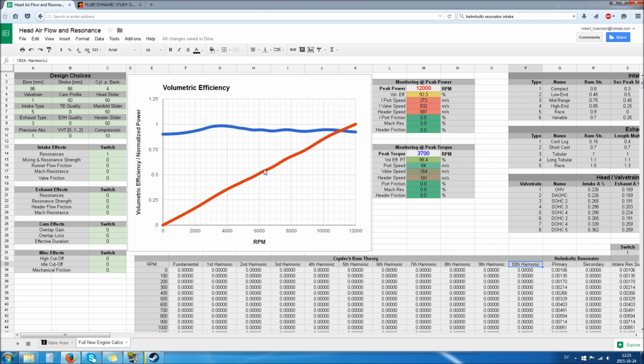And this bouncing back and forth can continue a while, as the intake valve stays closed. It is actually the second and third and fourth and fifth harmonic of this series which gives you some effects. That effect comes from when this shockwave gets back to the inlet valve, and that inlet valve is open. Then the shockwave will actually see to it that you get more air in than you would by only sucking on the intake runner with it being fully open. Quite an interesting effect.